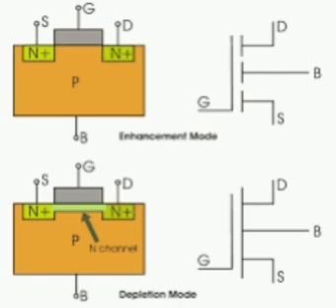CV characteristics of MOS: low frequency characteristics, accumulation, depletion, inversion. VF means flat band, VT means threshold voltage, VG means gate voltage. The drop in the capacitance is due to formation of depletion capacitance in series with the oxide capacitance. If C0 is known, oxide layer thickness Tox can be found as C0 equal to epsilon ox A by Tox. Tox equal to epsilon ox into A by C0, where epsilon ox equal to oxide permittivity.